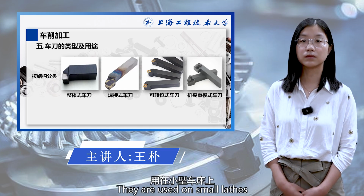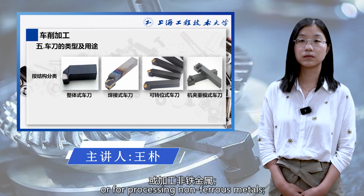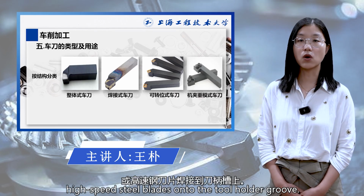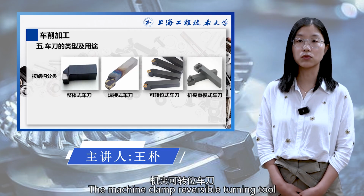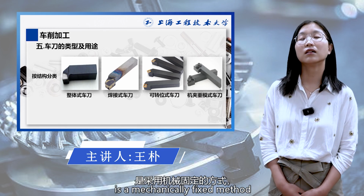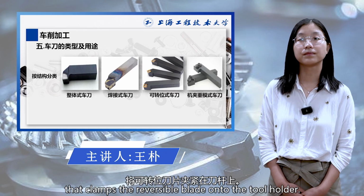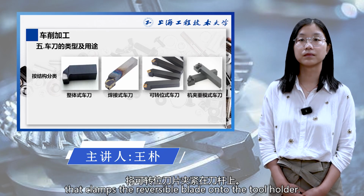They are used on small lathes or for processing non-ferrous metals. Welded turning tools are tools that weld hard alloy or high-speed steel blades onto the tool holder groove. The machine-clamp reversible turning tool is a mechanically fixed method that clamps the reversible blade onto the tool holder.